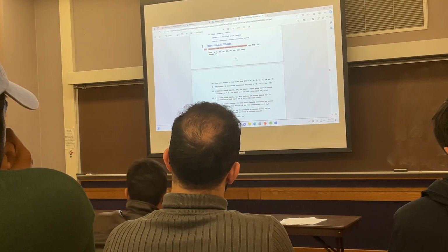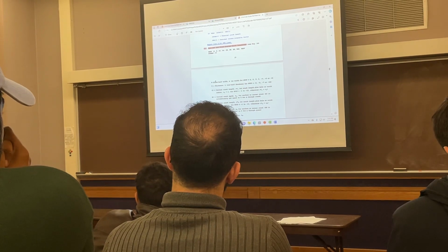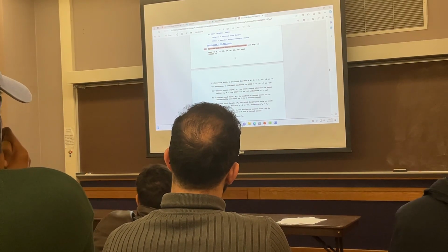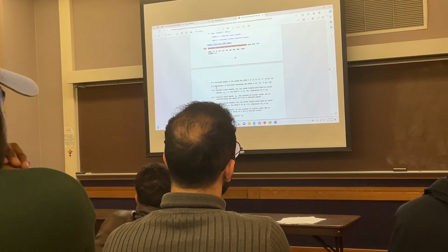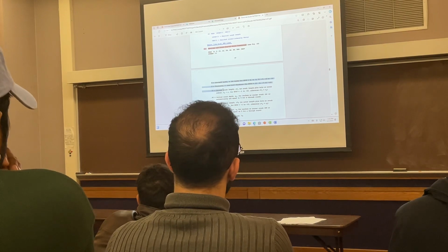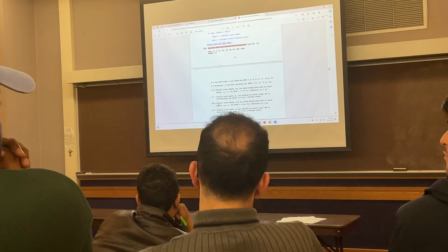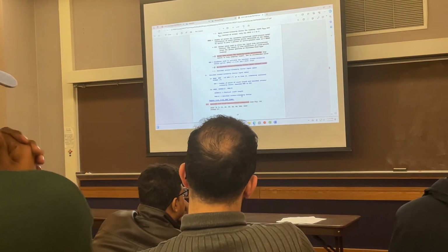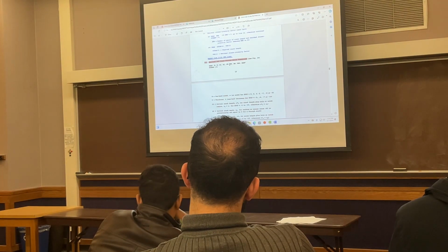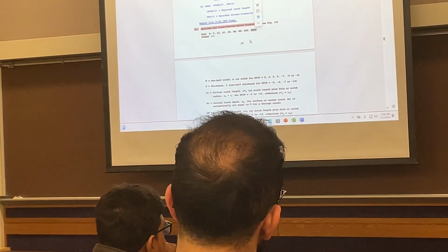So number 12 in the user guide, you see it reads WT, and there is a description for each of them. Read the description. Some specimens you may need to use just half width or the full width or thickness. So thickness, initial crack length, C and A in different directions. So just use that example as a sample for yourself, and you can find this. If there are other values, for example this one or this one, if you don't know what it is, just leave it at 0 or 1 or whatever is in that one.